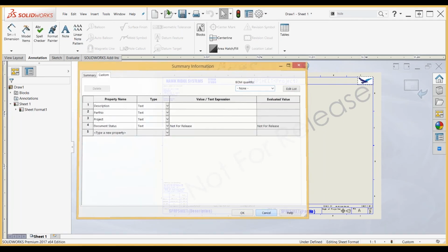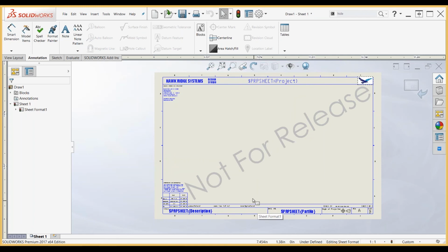I have all this information down here in my title block, and I want my drafters to be able to import the information here, but I don't want them to have to go down to the format level, because they might start to change line sizes, messing with this format, and I want that to stay nice and standardized.